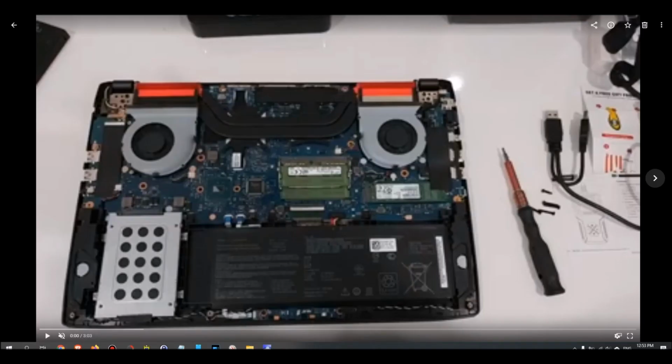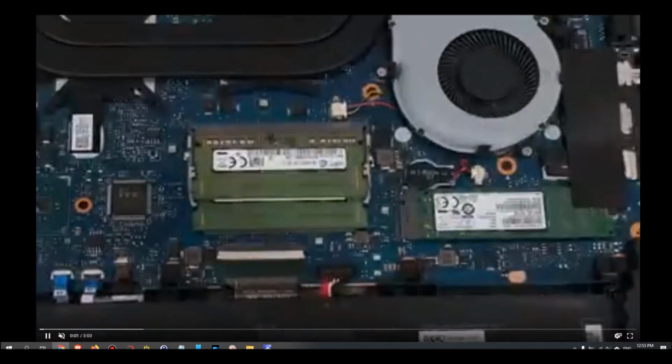It is even highly possible that your system has been collecting dust in some of the fans or all of the fans. There are sometimes housing fans, especially with the desktops, and you have here also these specific fans in laptops, and they are not accessible from outside. They are fully covered sometimes here, and the dust is collected here. Sometimes laptop design is good, so you can suck it up with a normal vacuum from outside, like from here, but in this system it's not possible. It was fully covered, and there was a lot of dust around here.